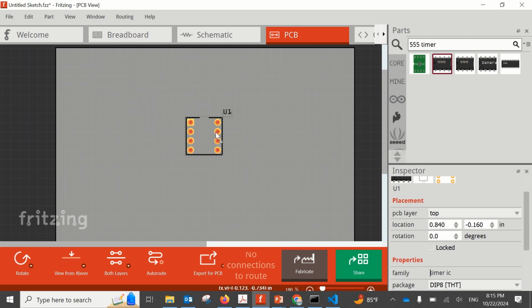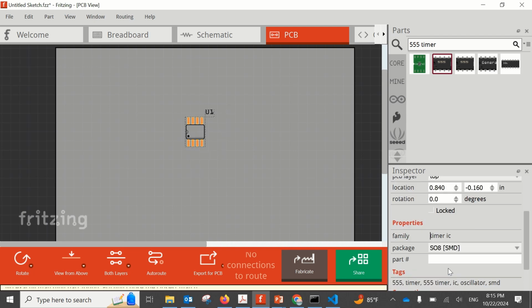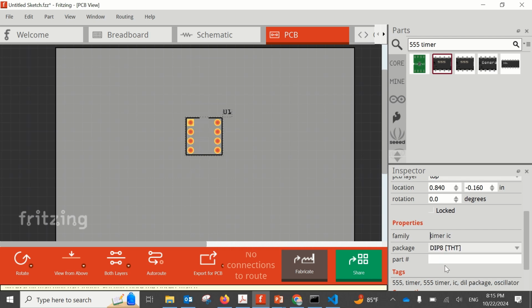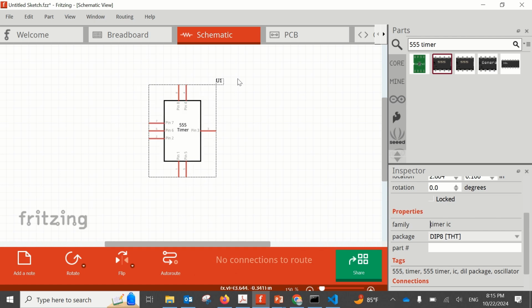If you're moving to a PCB design later on, let me show you how the SMD components would look. It's completely different. So this will affect your design and the holes and the routing of the PCB, so it's better to do it correctly from the beginning. Now, before even implementing your schematic, you should draw it on paper. You should design it and then implement it on Fritzing. This is better because it's easier if you have the final design and you're just copying it here rather than designing from scratch.